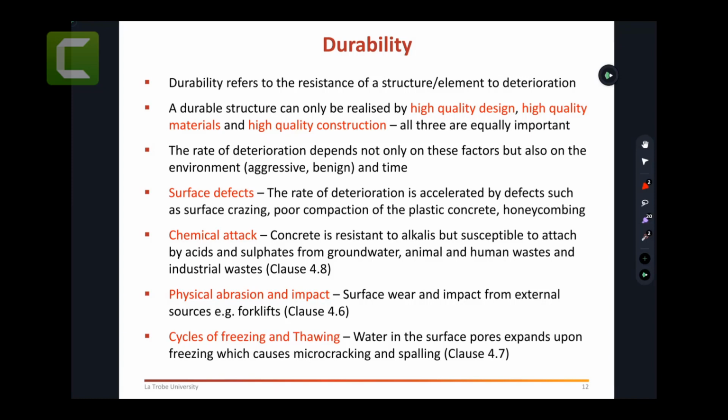Okay, as we said here, it is mostly durability to do with the environment, and those 7 classes I covered, as I showed you just before, depend on whether it's internal, whether it's external, whether it's exposed to running water, right? Whether it's exposed to soil with chemicals or without chemicals, they change. The worst case that you would see is concrete impacted by acids. And the slides will say this clearly. This is considered as class U.